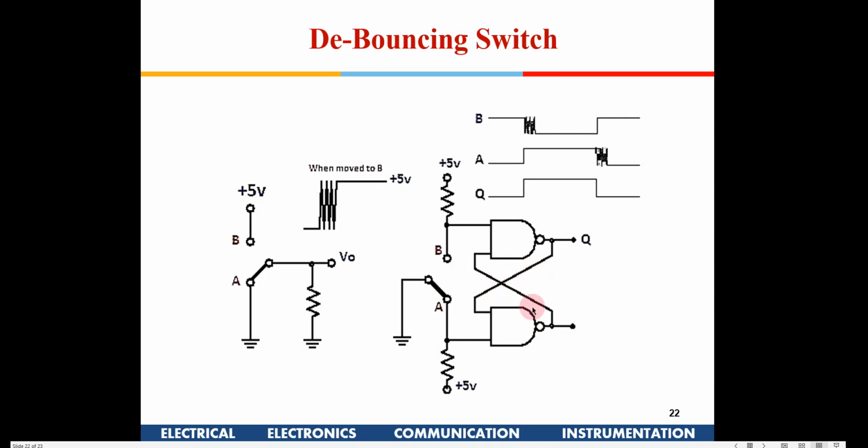So this is known as a debouncing switch. I just covered this aspect so that in case sometime in future you are going to use manual switches to give input to a microprocessor, then you might want to use a debouncing switch like this.